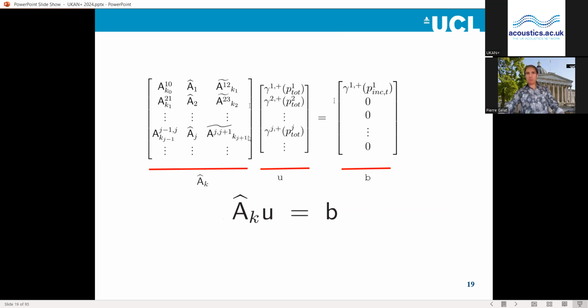You note that the left-hand side matrix is fully populated and contains complex numbers. You'd say, okay, that's all great. All we need to do is populate that matrix and invert it. The challenge here is that this type of system gets very large for the problem we're dealing with. So you can't have a direct inversion. You have to do an iterative solve, and we use the GMRES method.